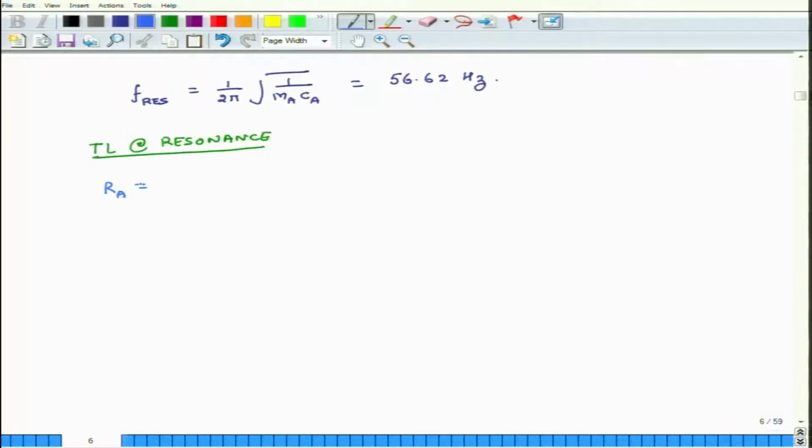So, RA is what? This is the acoustic resistance of all the 3 pipes combined. For one pipe, and this pipe has a mesh, it is Rs divided by pi a square, and because there are 3 pipes, we divided by 3. So, the mesh is having how many wires per inch? 100 wires.